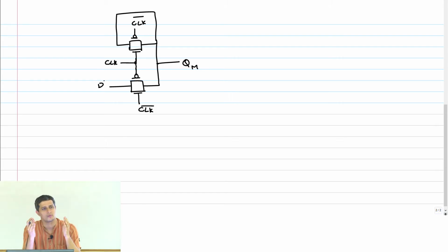What does characterization mean? It means that as a standard cell designer, I design a gate or a flop, and then in your assignment now, you are characterizing the delay of an adder against the loads, against the slew. You're basically saying if the load is this much, the delay is this number, and I should be able to give you that number. That is what is known as characterization.